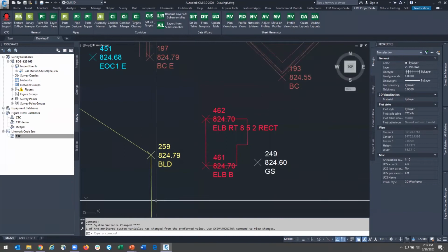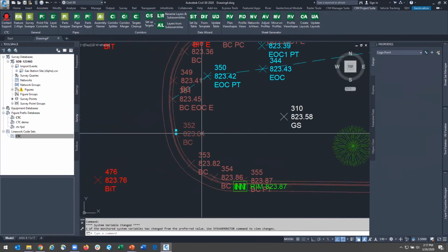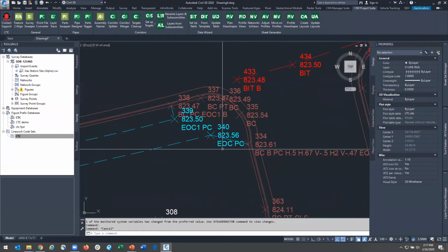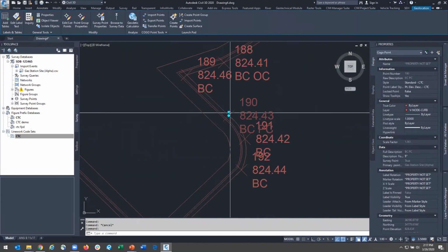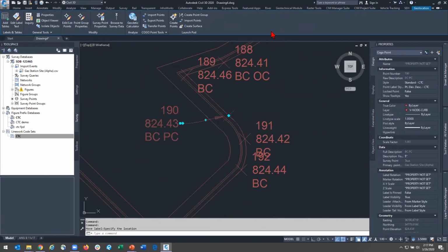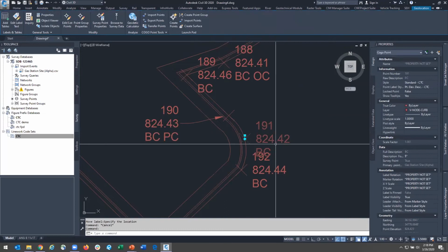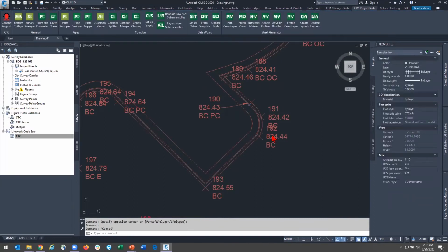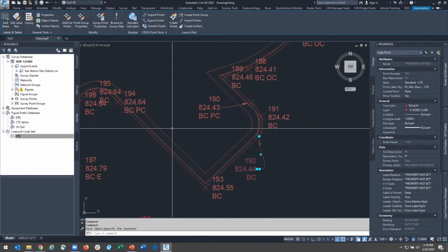We've got curve codes. So I can come over here and I can say point, that one's a little dense for me. Point 190. As I'm coming to the south, and so on and so forth, I'm saying PC, begin a curve. And I can go through and I can have 191, okay, whatever, that's on a curve. And then over here on point 192, it's just automatically drawing a 3-point curve based off of the rules of those curve parameters.